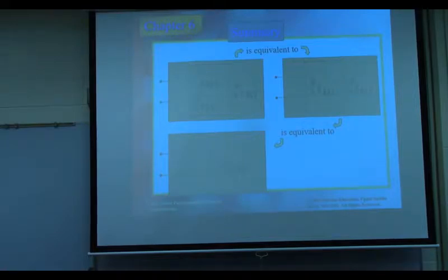what is it? Suppose now you have the ohmmeter, right? You measure the resistance. In the homework we tested you how to measure the resistance, right? You know that. So you just put the two terminals. First, you need to disconnect the circuit from the source. Then you put the two probes to the two terminals, and you measure the first one. What is the resistance? What's the reading? Oh, looks like we don't know.